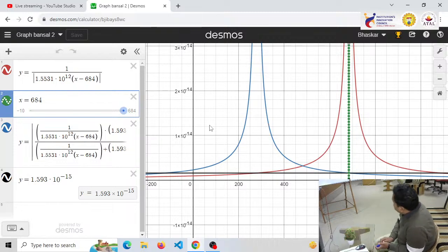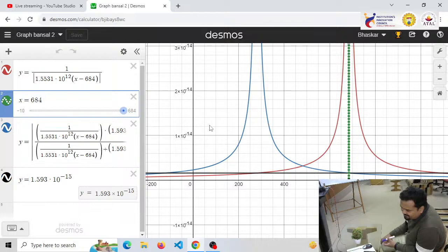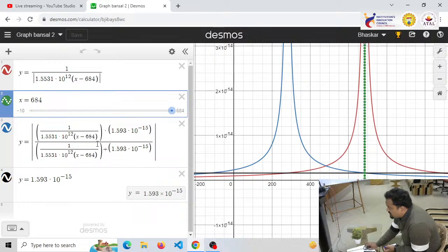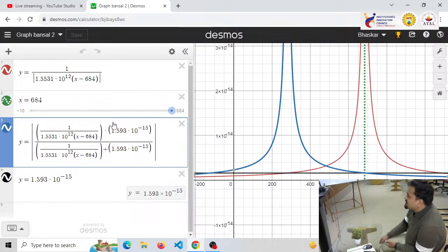Now as I told when I was explaining on the board, heterostructure means there is a series combination of two capacitors. So equivalent capacitor will be C1 C2 upon C1 plus C2. So if you see, this is the C equivalent, and this is C1. C1 is ferroelectric, C2 is dielectric. Please note down here that for the dielectric capacitor, I have taken the material as silicon dioxide, SiO2, with a permittivity of 3.9.